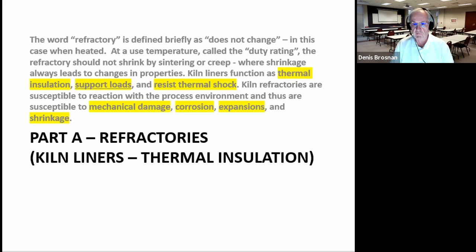Okay, well, let's talk about refractories. The word refractory means that something does not change. In the case of kiln linings, the internals in kilns, we don't want these refractories to shrink as they are increased in temperature. You can apply the word refractory to other things like human beings even. If a person doesn't change their opinion ever, then you could call them refractory. But in our case, we're only interested in the thermal response of the insulation and to make sure that this insulation does not shrink at the temperature where we're using it, because shrinkage causes all kinds of difficulties.